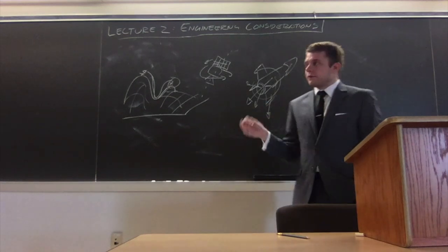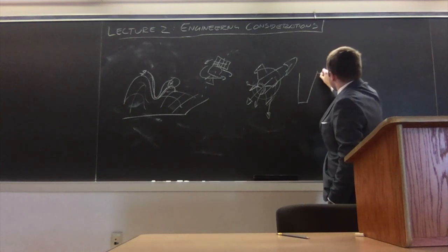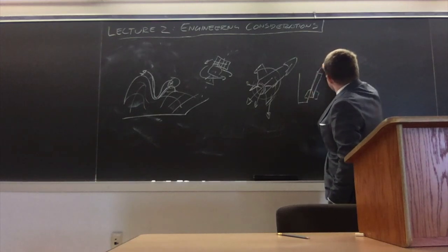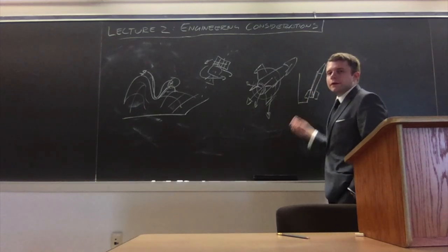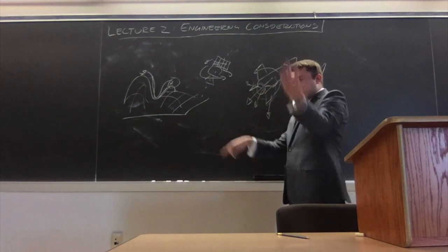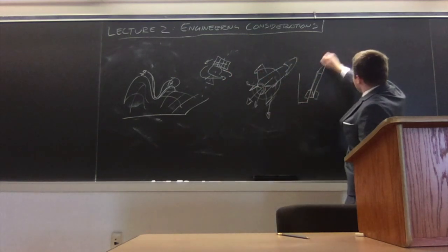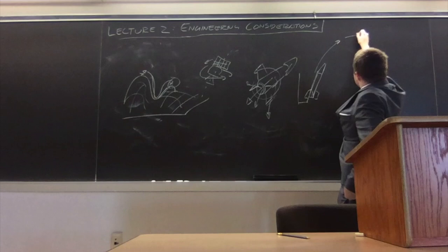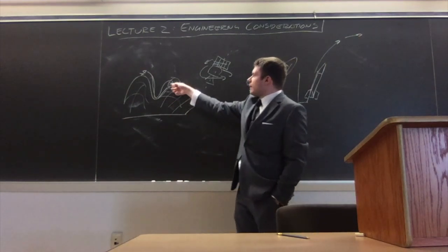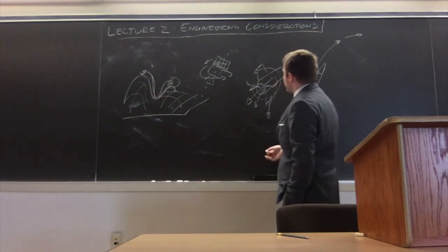So for our considerations, of course, we're talking about basically building a rocket that is all solid, has no active stability on board, and launches off of a rail. And that means that you pre-program that spin into the fins. You take the fins, you actually angle them a degree or two. And as the air flows past it, it's asymmetrical, so it spins up. So it launches off the rail, and it starts spinning. And then it gets up to space, and it's still spinning. It's nice, it's stable, it's happy, it's living at that little energy state right there where something has to happen for it to pop up to that other higher energy state.